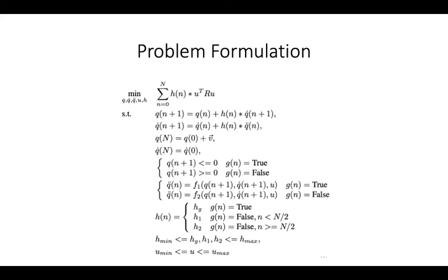To get the robot to hop up a set of stairs, I imposed the constraint that the initial and final velocity were the same, very similar to most gait problems. However, I gave the additional constraint that the final position was equal to the initial position with an additional displacement, allowing for the hopper to move up a step at a time. I also imposed dynamics constraints using a backward Euler approximation.